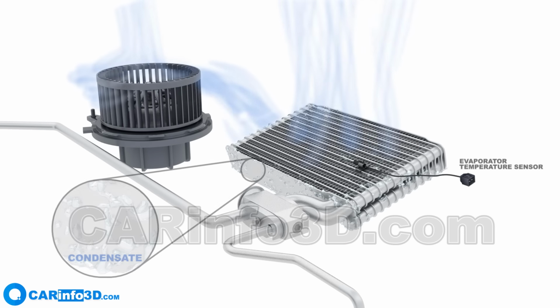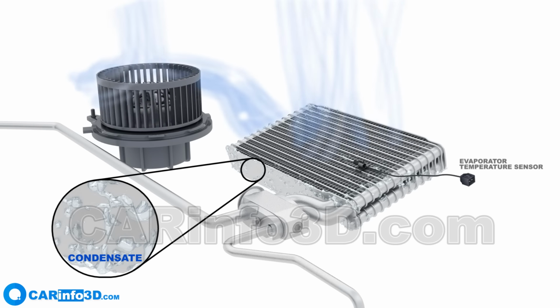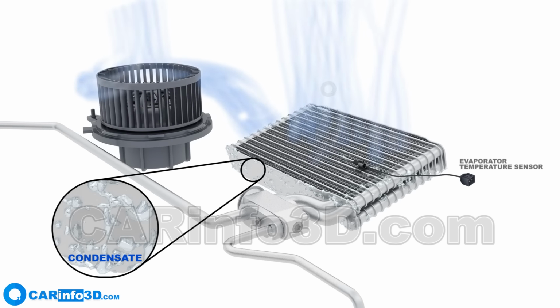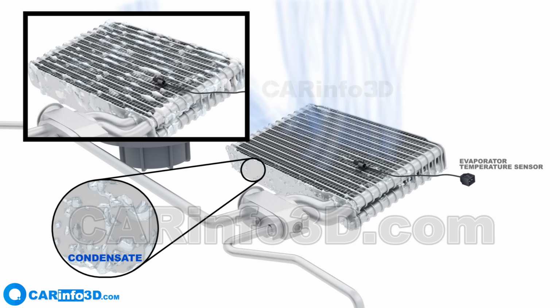This requires some explanation. If the air temperature drops below freezing as it travels through the evaporator, the air conditioner will cut off to avoid the condensed moisture from icing on the evaporator. Condensation on the evaporator's surface and probable drainage under the automobile is a normal occurrence.